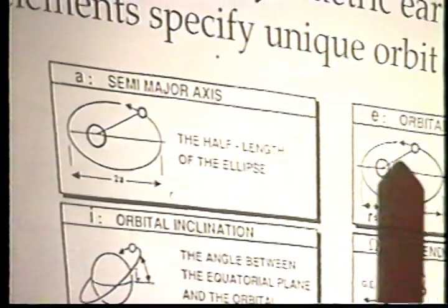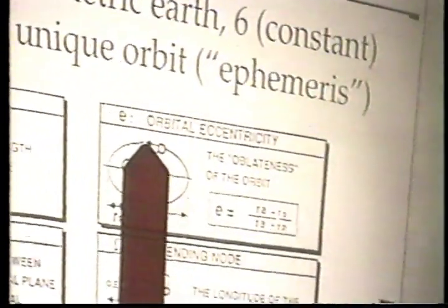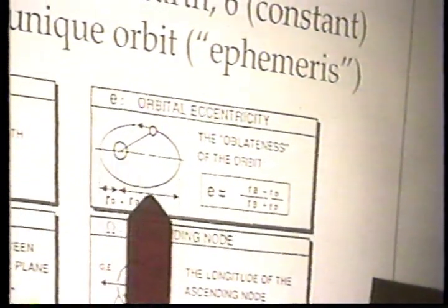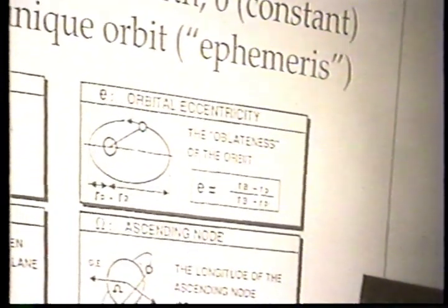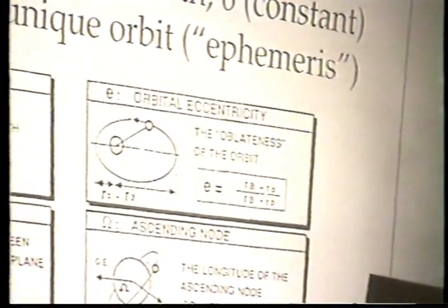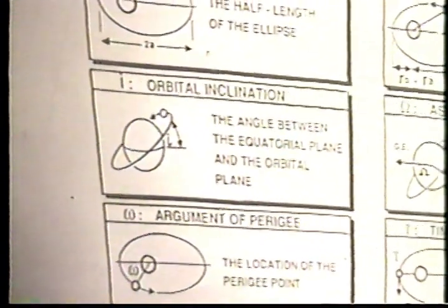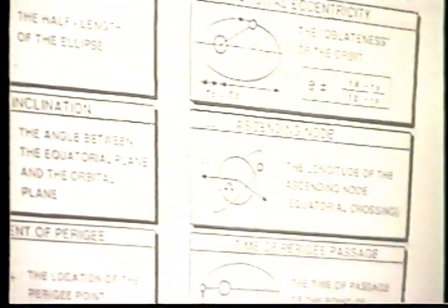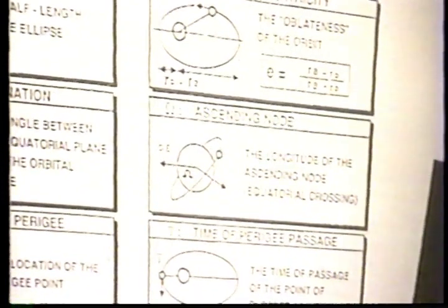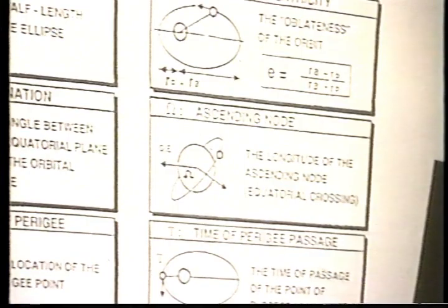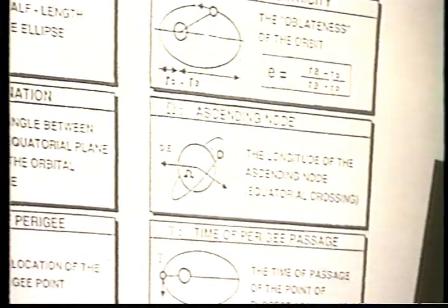So that's one parameter. A parameter which measures how much the major and minor axis differ, called the eccentricity, is controlled very well when they launch, or they correct for launch errors. They keep the eccentricity less than 2% in the system. There's the inclination I explained already, 55 degrees. The nodal thing tells you which plane you're talking about.